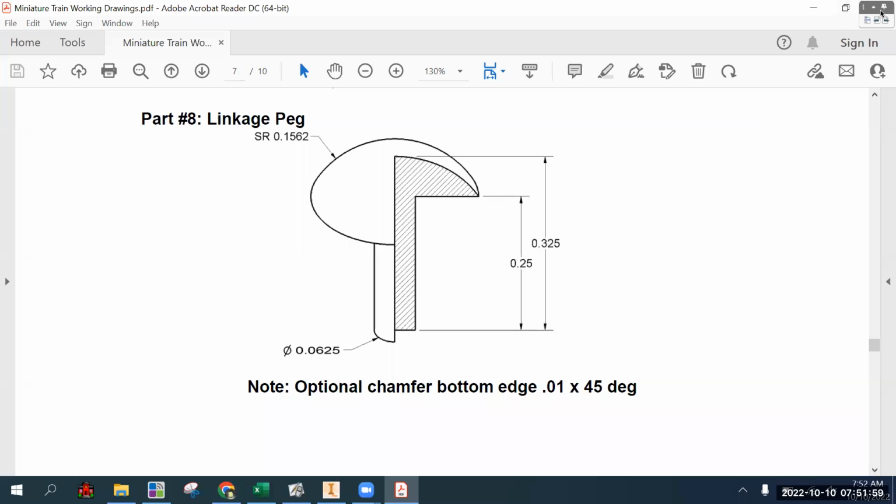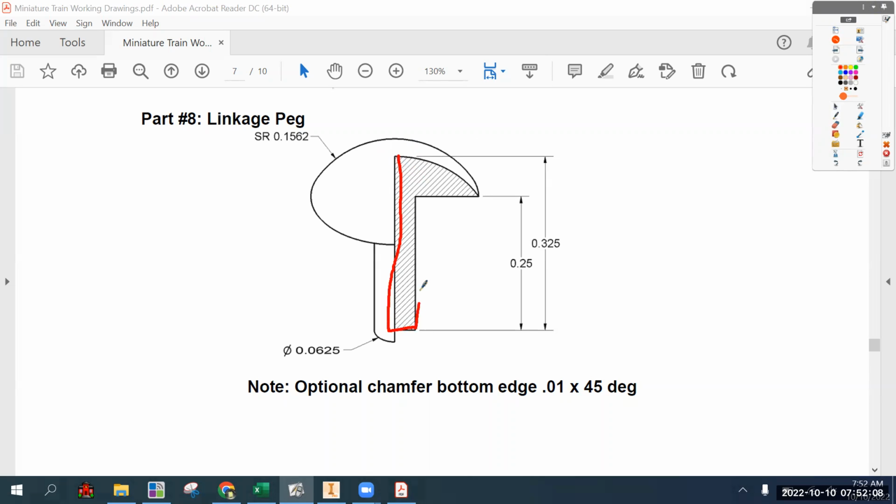The easiest way to do it is going to be what's called a revolve, where the sketch you make is actually just sort of the right half of the part, and then you revolve it around instead of extruding in a straight line and like squishing the Play-Doh out of the little star-shaped nozzle. This is revolving it, taking whatever sketch and revolving it around whichever axis you choose.